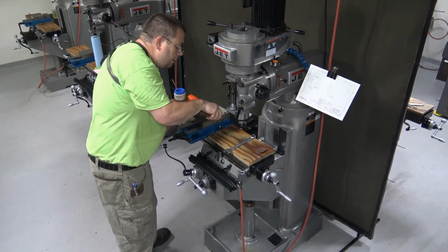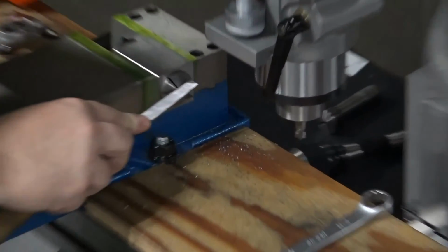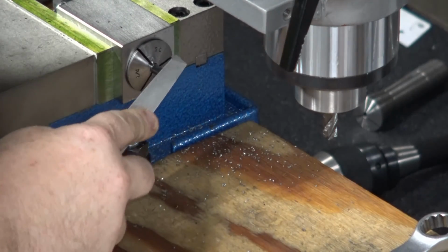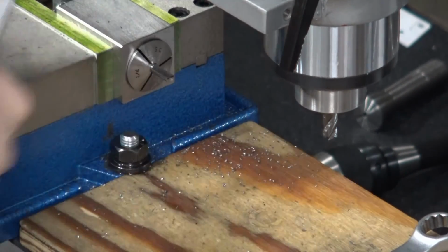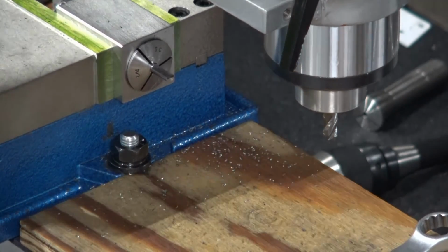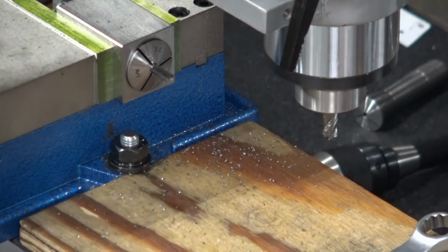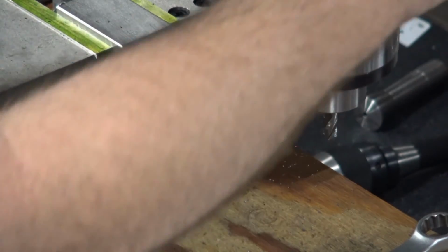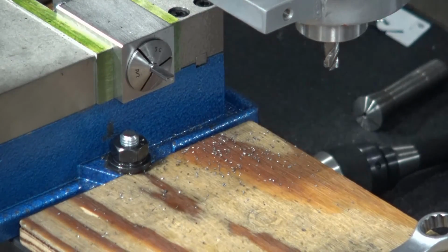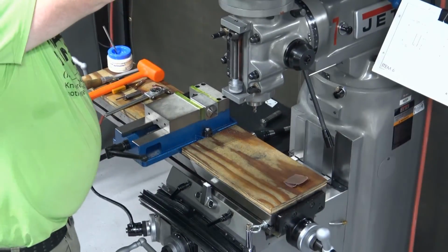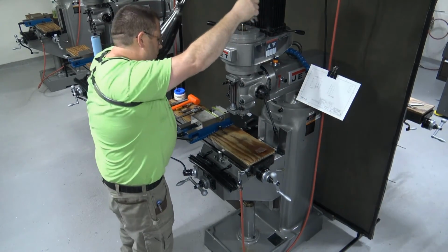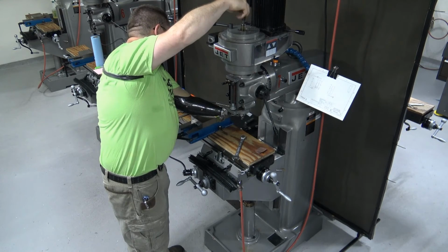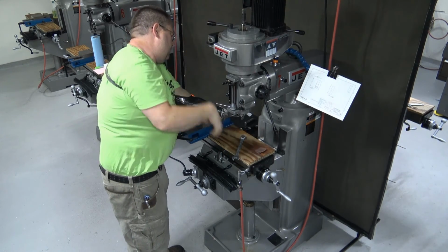Now I'm going to deburr both sides of the flat and the end of that flat. Because when I set up to do the drilled and reamed hole, any burrs on those edges is going to or could possibly affect my ability to set that position. Let's go ahead and bring the quill up out of the way. While we're close by here, I'm going to loosen the drawbar. We're going to switch to our drill chuck. Okay?